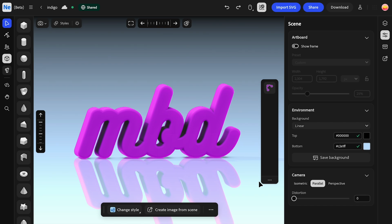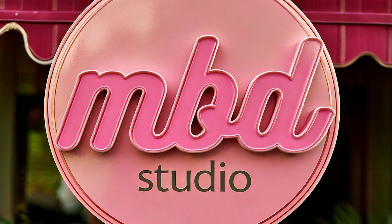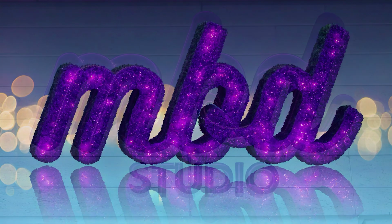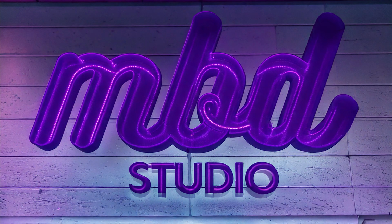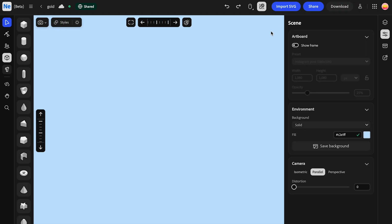under 10 minutes. So before we get started, I do want to remind you that in the end, I'm going to show you how to do some of these really cool mock-ups using Adobe Project Neo after you create your 3D logo. So once you've logged into Adobe and you've gotten to Project Neo, go ahead and click on the Create button. So the first thing you're going to do is import your SVG logo.